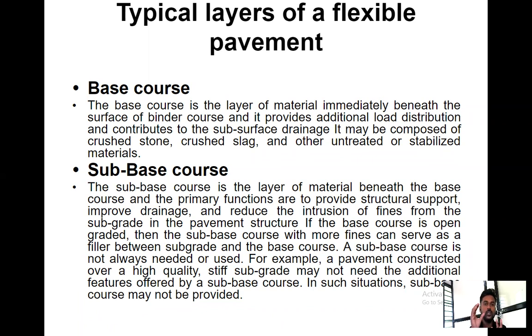If there is a lesser load, we can directly transfer the load from the base course to the subgrade. It depends on the loads. Whether we should provide these layers, and how much the depth of each layer should be, depends totally on the load coming on the pavement.